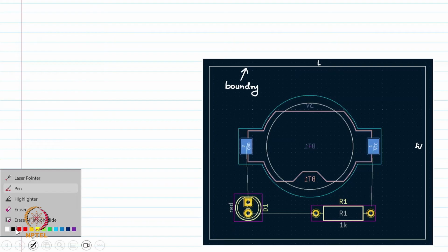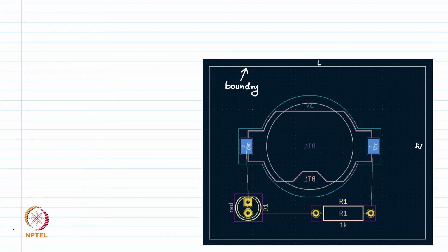So the imported footprints, first they were in random fashion, now we need to take them apart and place them uniformly. For example, this LED earlier was somewhere here. We want to place it in such a way that, looking at the rat nest, these wiring information, we place footprints such that fewer rat nests are overlapping each other.